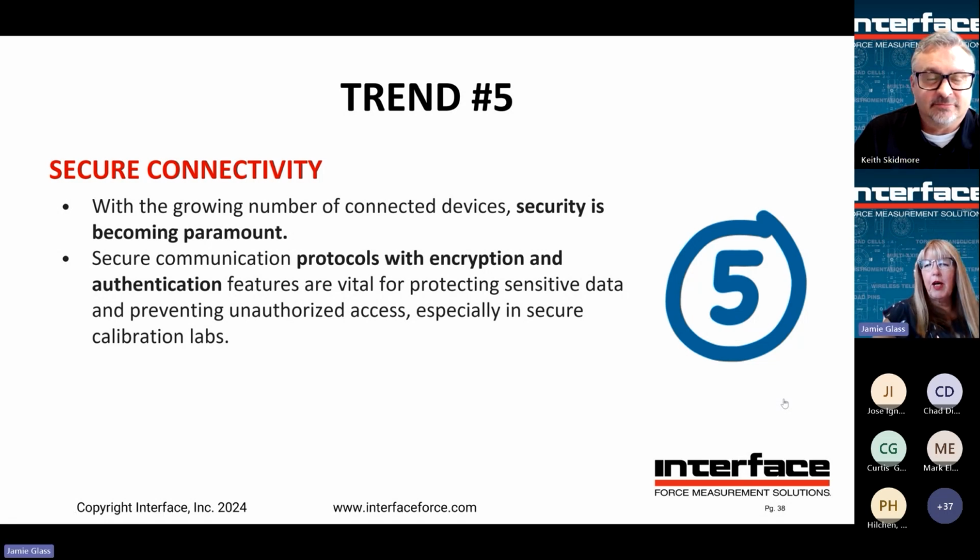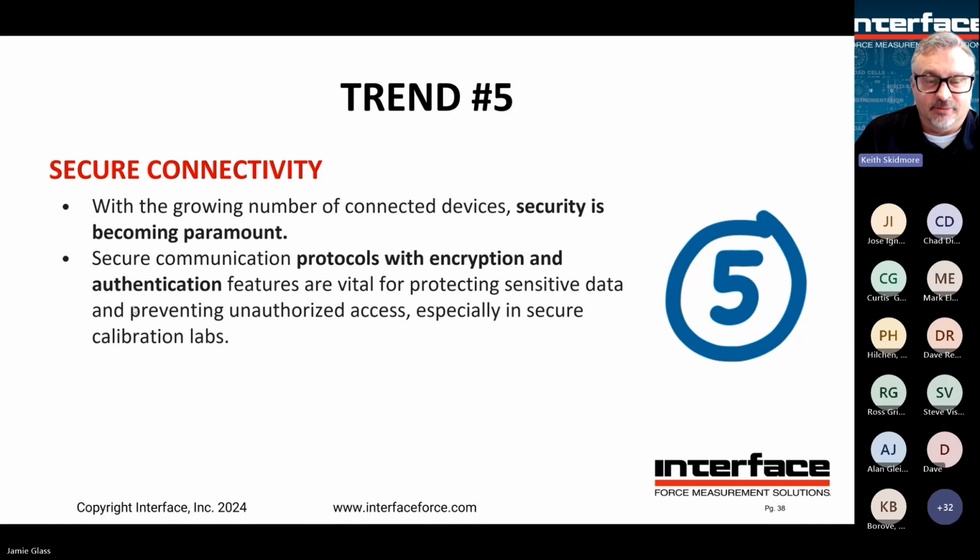Yeah, Keith, there's another question about which wireless protocols your products use and what security settings are available. So the WTS products use 2.4 gigahertz, so basically standard Wi-Fi. Typically it's not at all encrypted. It is a proprietary protocol, so it's not so easy to interpret, but certainly easy if somebody were to buy the right equipment. But there's a feature that can be enabled that adds encryption, and so it encrypts the data. So it's not only over the proprietary format, but it's encrypted within that format. And then you've got to be careful you don't lose the encryption codes.